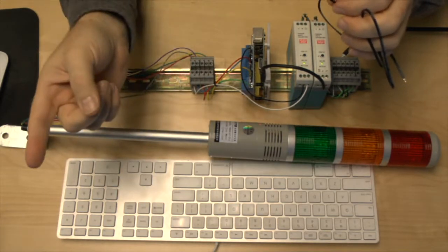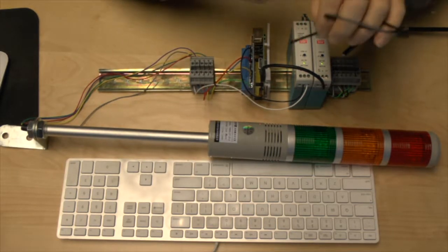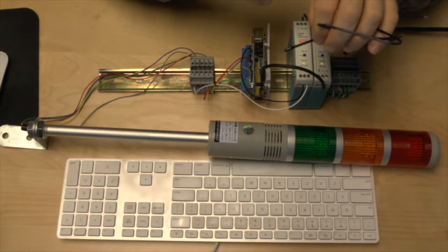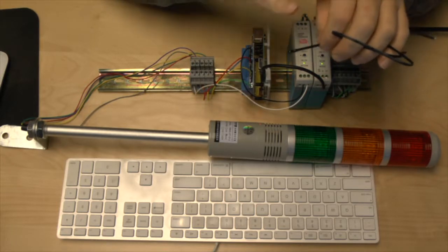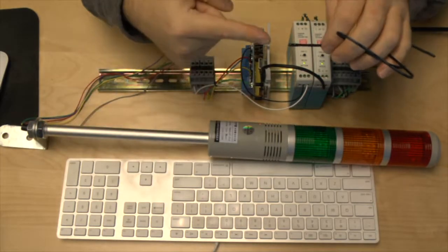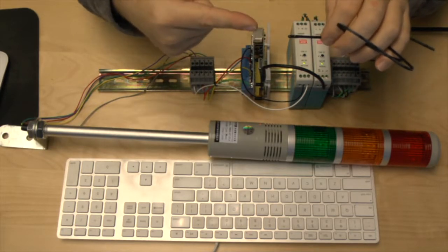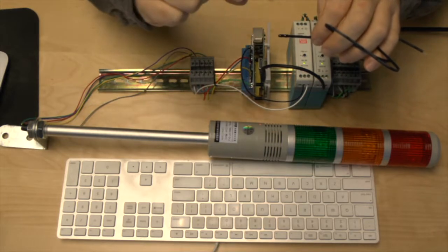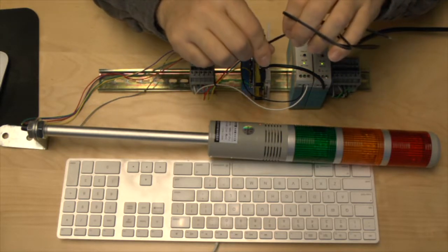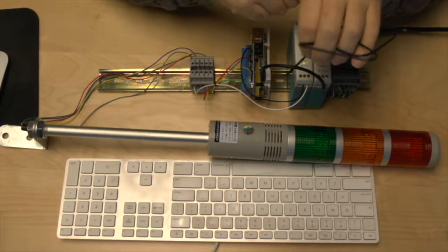Well, the pipe's serialized or lot numbered, and we can go all the way back and find the work order that we used to build the pipe, and we know the start time and the end time of the operation on the work order when we ran the extruder, and we can go to big data, and we can look at second by second the temperature on that extruder motor, or the extruder heater, to figure out if we were extruding at too high or too low a temperature. You can keep that data forever.